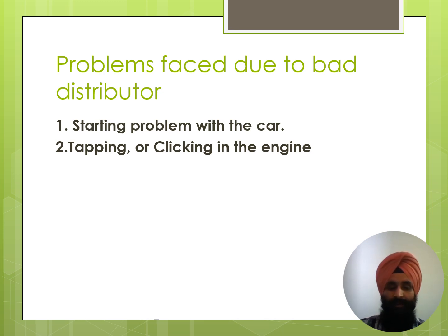So probably the problem may be in the distributor. Second, tapping or clicking in the engine. This is also very common. You all have seen that in old model cars, these tapping or clicking sounds are generally due to a problem in the distributor.